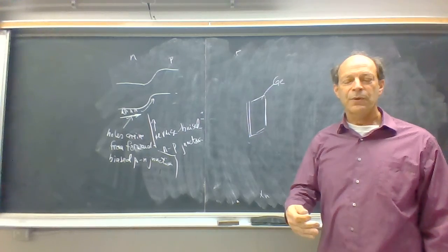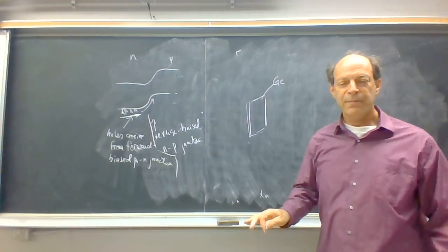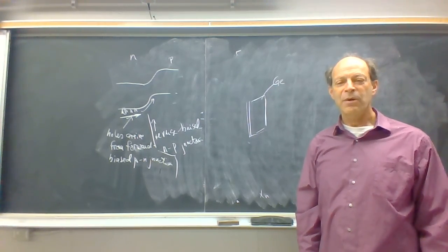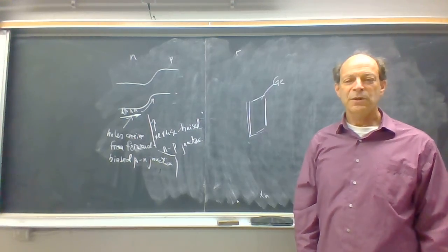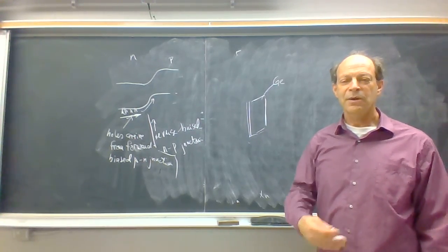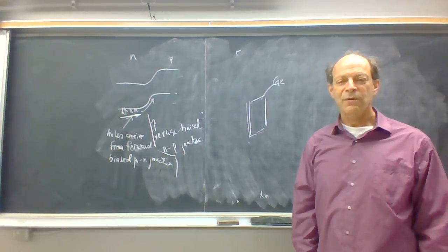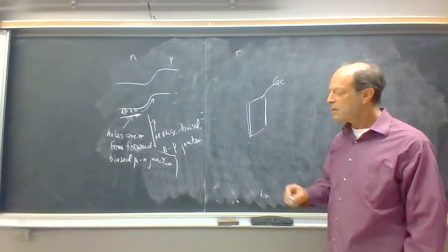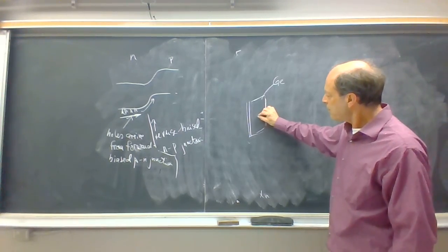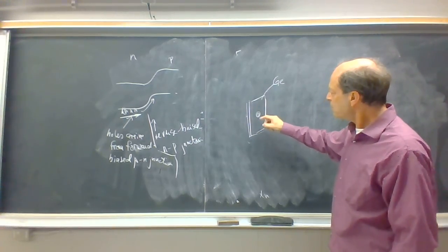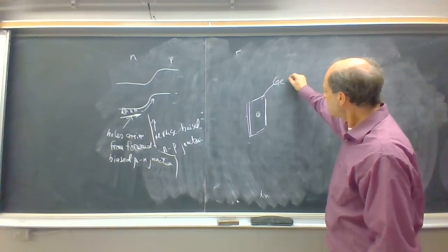So you can make a very good germanium bipolar junction transistor. It doesn't quite have the ability to tolerate higher ambient temperatures, and germanium is much more expensive than silicon, so germanium quickly gave way to silicon as the transistor developed and matured. But the early transistors were all made of germanium, and at Bell Labs they created a P region on this germanium. So the germanium was actually N-type.